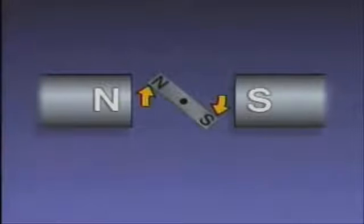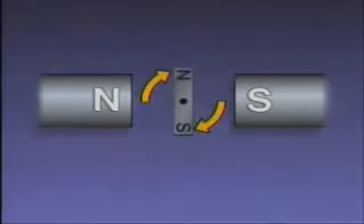In order to show how the magnetic field around the loop interacts with the magnetic field of the permanent magnets, we'll represent the poles of the loop with a bar magnet. The bar magnet is pivoted so that it's free to rotate. With the bar magnet in this position, the two north poles are next to each other, and the two south poles are next to each other. The like poles repel each other, so the interaction of the magnetic fields causes the bar magnet to rotate. The rotation or movement of the bar magnet is an example of motor action.